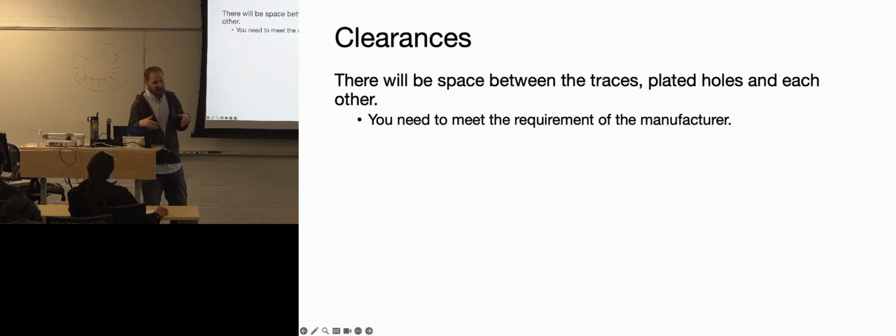Doesn't mean your entire design should be 6 mils. That might be risking things. And certainly for signal integrity and power consumption reasons you might want to definitely have larger traces, but they're saying 6 mils is the smallest we can make. The next one is clearance, from one trace to another one. What's the minimum clearance they can have? And typically, for JLC PCB and PCBWay, that's like 6 mils as well. So it would be 6 and 6. But sometimes you might get down to 4, depends on what you're looking for. It depends what you're willing to pay.